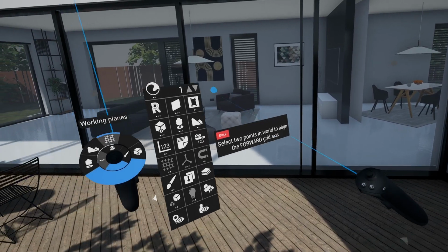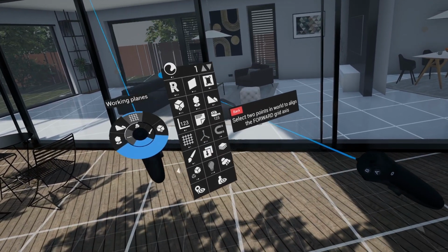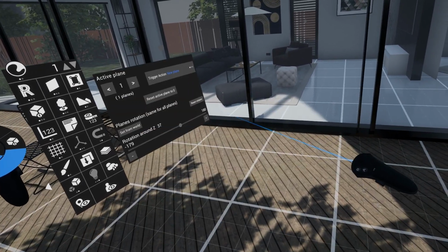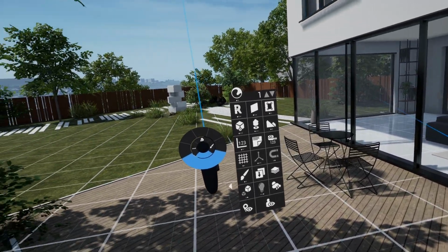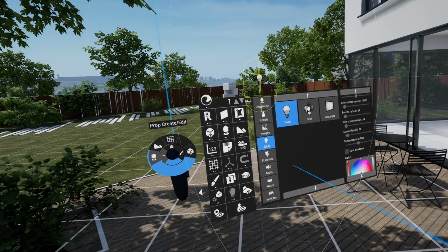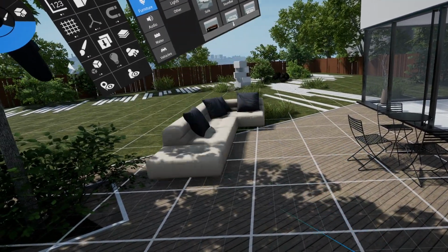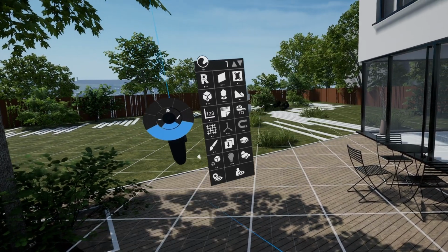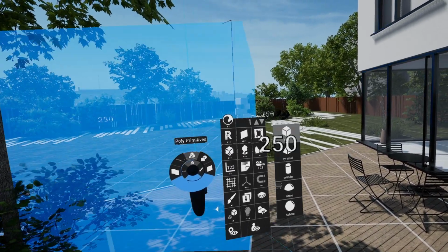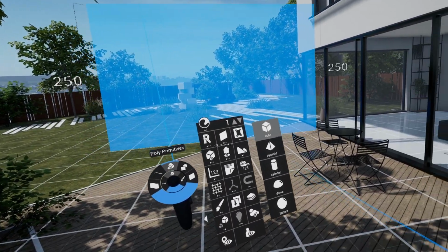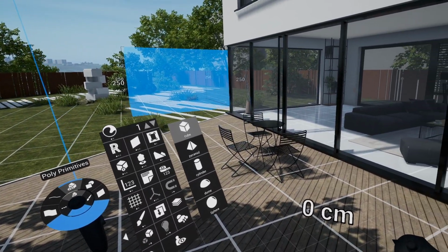Let's turn on the grid, you see, on the ground, and let's rotate this grid in a different direction, this direction. It means when I create something, for example, from our library, it will be rotated to this direction. And if I create spaces, it will be rotated in this direction, exactly like I want it, so it will be like the facade that I see.